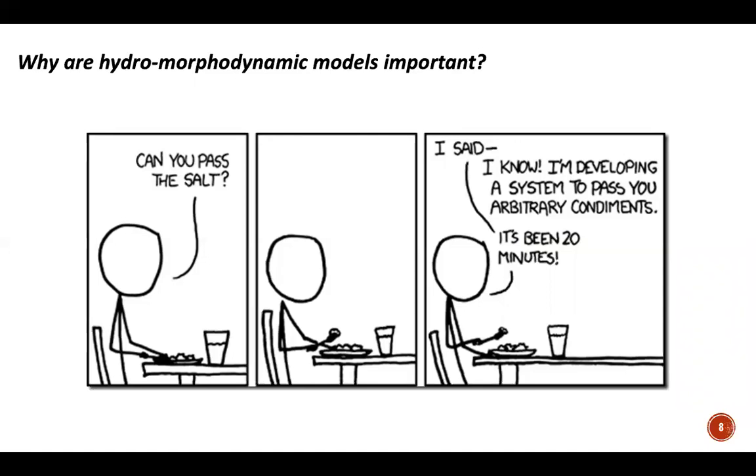You have a real danger of over-engineering. So you could build a huge massive wall which stops the waves or stops the erosion, but that might actually have negative impacts downstream. So you might get more erosion downstream. You're also affecting the sediment flow. So there might be areas which are reliant on deposition, which are no longer getting the sand deposits they need. And there might actually have been a simpler, cheaper option anyway, which would have stopped the waves or stopped the erosion, which you hadn't thought about because you've gone straight towards this huge coastal structure.